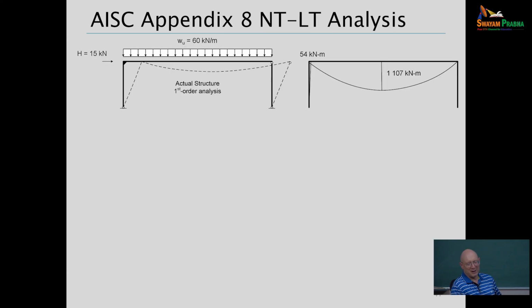So related to that, would I have any thrust at the foundation? Usually if I have a portal frame and I put gravity load on the roof, I get equal and opposite thrusts at the foundation, right? Any thrust here? What's going on with the column on the right? It's a leaning column. So you can't take any shear? Right. But if there's no lateral load, there would be no thrust, right? Because the leaning column cannot develop any shear. That's basically what you were saying, I think. Does everybody see that? We need the mic so we can hear.